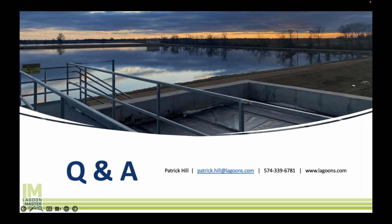Does the complexity of the recycle require an operator training level increase? And is this an automated system where it's just consistently going around and around? There are two ways to do it. The short answer is that it doesn't require more training. Think of it as a pump station, like any lift station within your collection system. If they're operating pump stations, the recycle system is a pump station. It's basically exactly the same equipment.